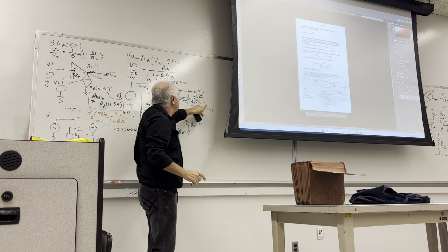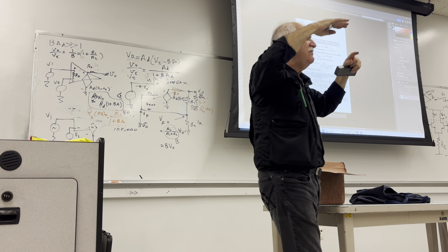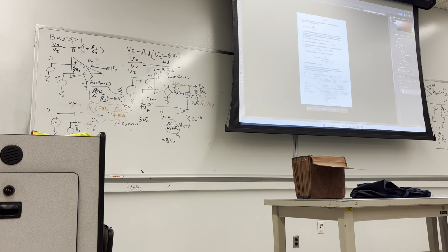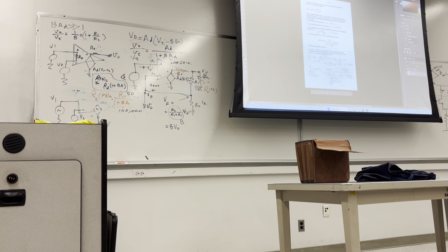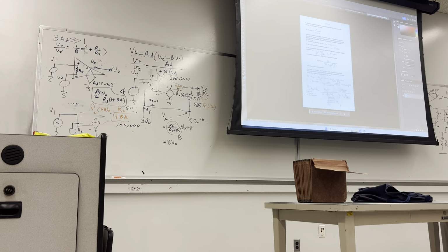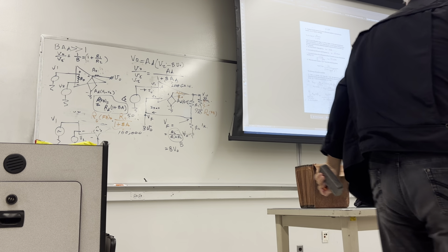So when you put the speaker in, the output level is not going to drop. The amplifier compensates for that. Your feedback compensates for that. Have you noticed we've got this much output impedance, and then how come it can feed an 8-ohm speaker? An 8-ohm speaker has such a low resistance, so why doesn't the output drop when you connect it? Well, because it has a feedback mechanism which automatically reduces the output impedance, makes this thing ideal.